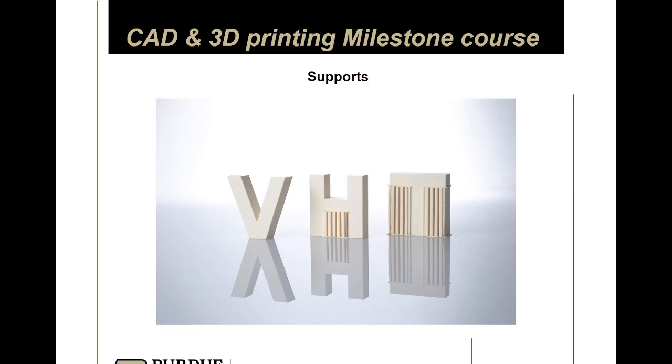Yeah, you could print it upside down. You could also just print it flat too, right? So print orientation is something you might want to think about when you're designing stuff, because sometimes people print things in really strange ways to minimize the amount of supports. The other reason people might do that is to help with surface finish.